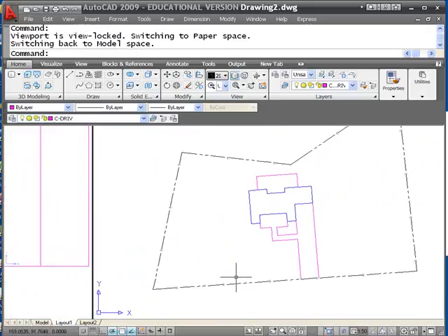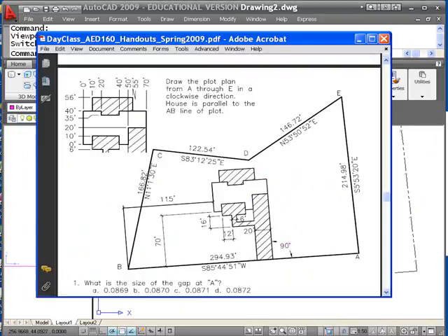But what I want to do now is put dimensions on here, and the civil dimensions are going to be put on there so that the distance is above and the bearing is below. By the way, when you do this in AutoCAD, you're going to have the numbers over here flipped. Don't worry about it. This would be more appropriate, but it's a little tricky actually to get AutoCAD to flip those for you. So we're going to have the distance above and the bearing below.